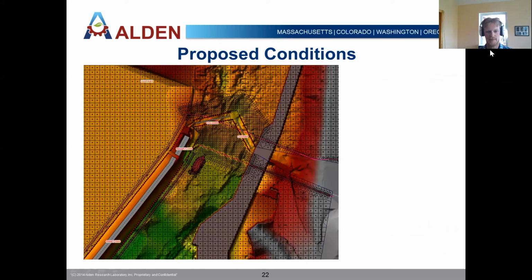So here's what the final proposed conditions laid out. Despite having all this other spillway crest on the western side, it was decided or preferred to do this V-gate scenario so that you could increase your total spillway length despite your fixed existing crest length. This V-gate configuration with that streamlined profile was able to compensate for the loss of spillway due to this fish ladder, which is completely ineffective flow in the model. So there's no overtopping at all.